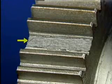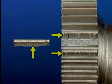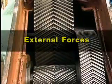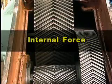The appearance of a break that has been caused by overload can be described as being rough. In addition, the gear tooth broken by overloading and the adjoining gear teeth may be deformed or damaged, and in some cases of overloading, all of the teeth on a gear may be deformed or damaged. An overload which causes a break may have been caused by forces external to the gear set, or it may have resulted from an internal force.